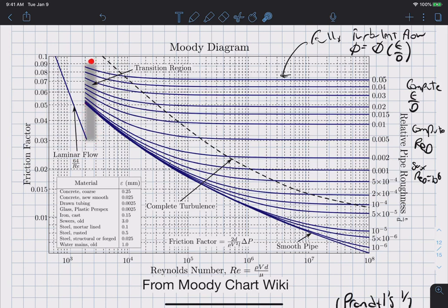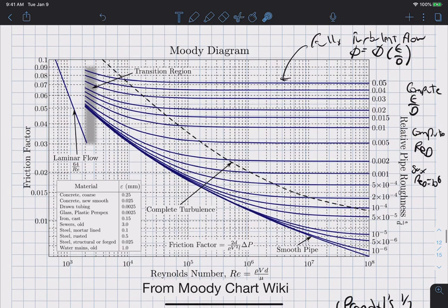We're not going to get into transitional turbulence in this class, but there's no such thing as a state that's halfway turbulent and halfway laminar. At various times, the flow is either laminar or turbulent. It is one or the other. And so if you have a transitional turbulent flow that's here, in some locations the Darcy friction factor will be here, where it's laminar, and in regions where the flow is turbulent, it will basically jump up to there.